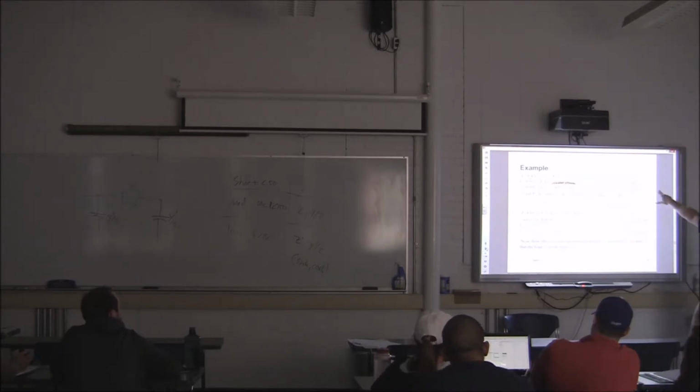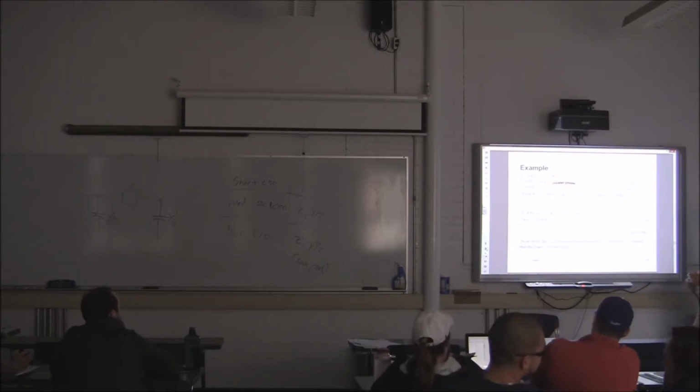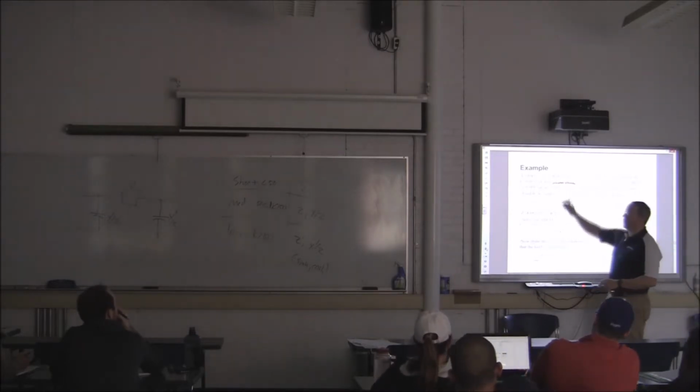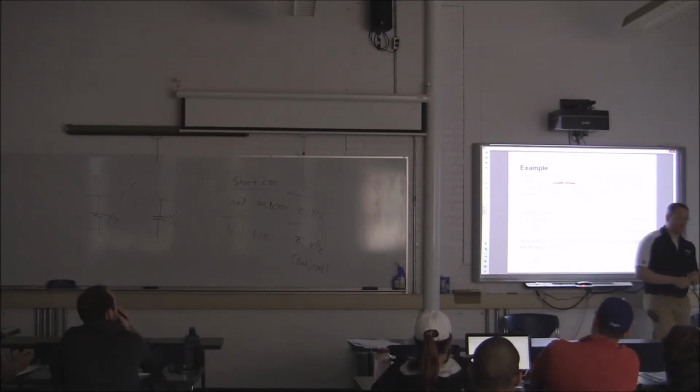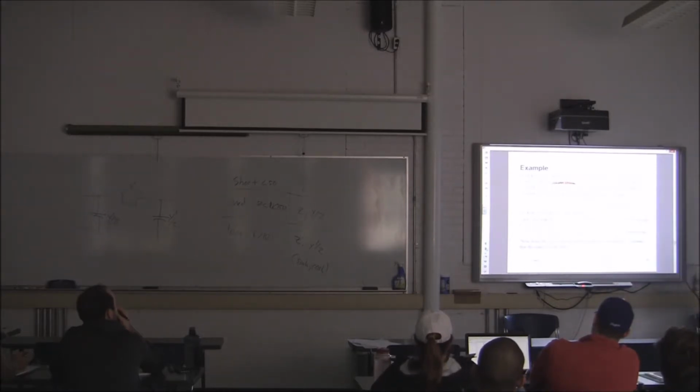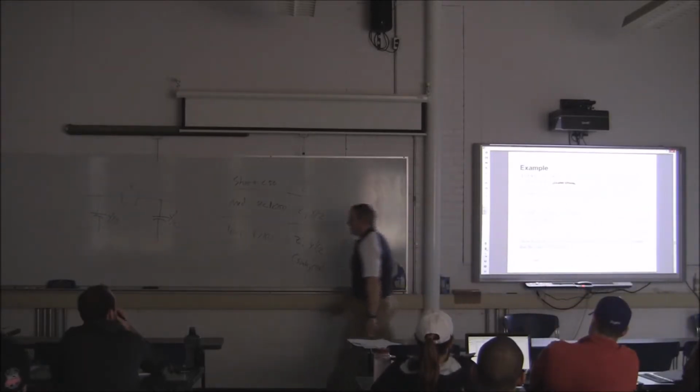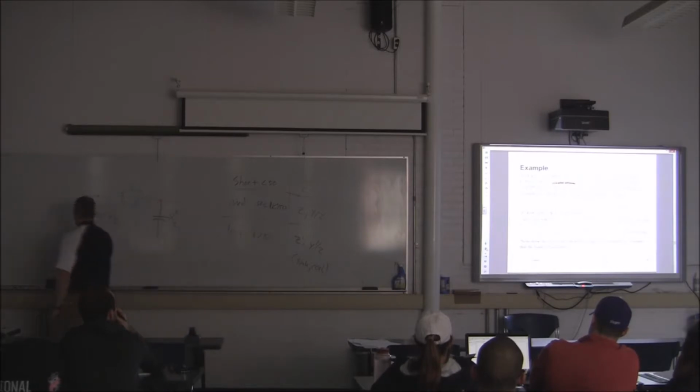Receiving end load is 270 MVA at a 0.8 power factor, lagging, and its nominal voltage at the receiving end is 325 kV. Okay? So, if that's confusing, draw a picture. 130 kilometers.